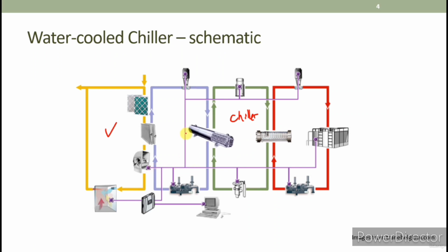And by the way, the purple lines are representing the control loops. That is why it is linked to the thermostat, valves, and fan, as these are the inputs and outputs to maintain the space at certain temperature or condition. It is also sending information to a computer, which houses the building management system, or usually we call it BMS.